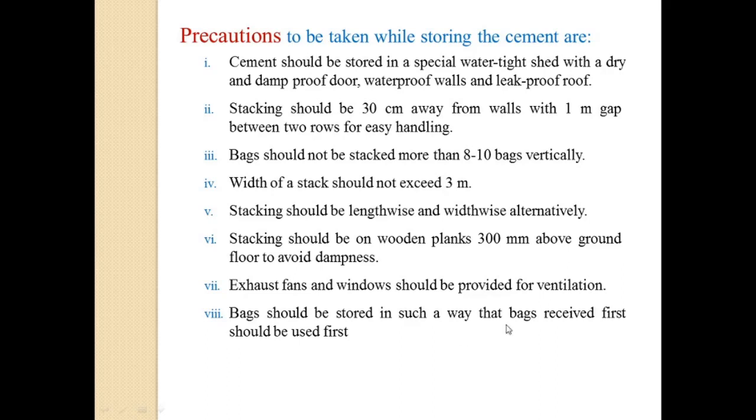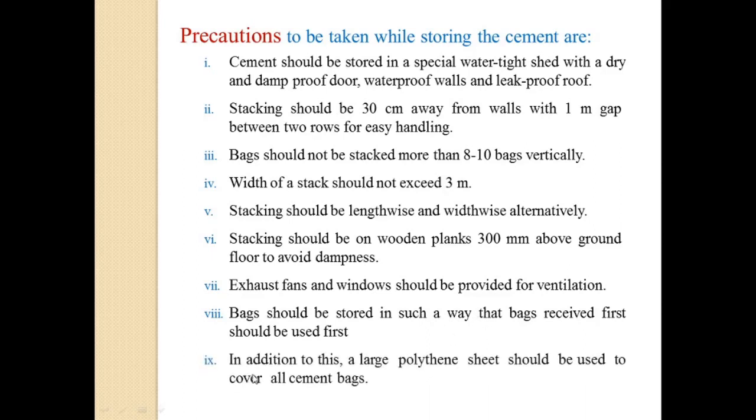Next, the bags should be stored in such a way that the bags received first should be used first. This is a very important point because if cement bags are stored for more than 3 months, it reduces their strength. So the bags which are received first should be used first, to avoid the strength loss. In addition to this, we can use a polyethylene sheet to cover all the cement bags, so the water or the dampness should not affect them. These are all the precautions we have to take while storing cement.